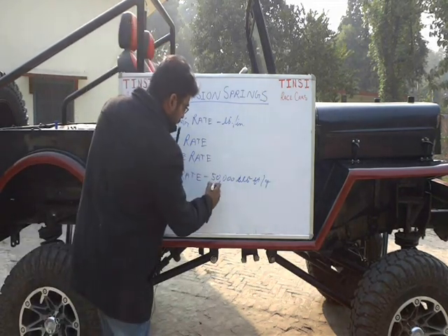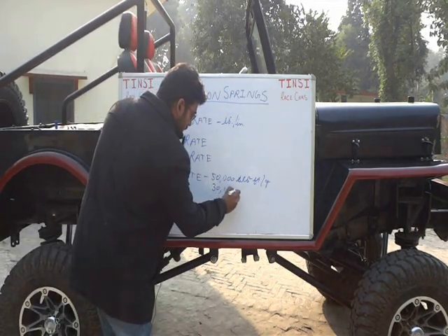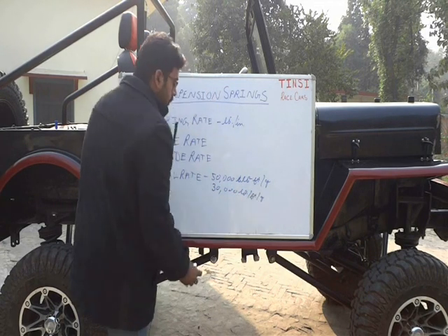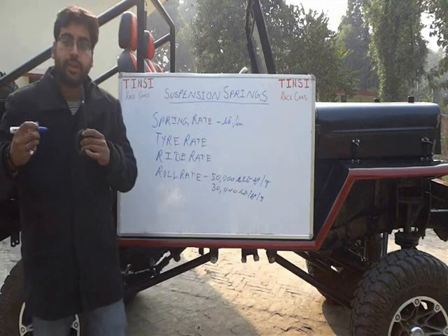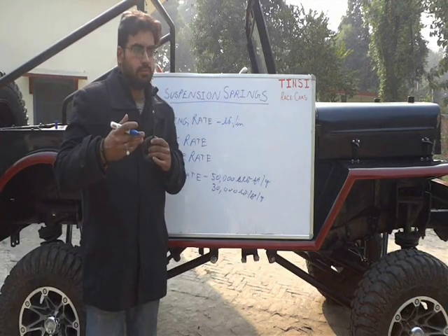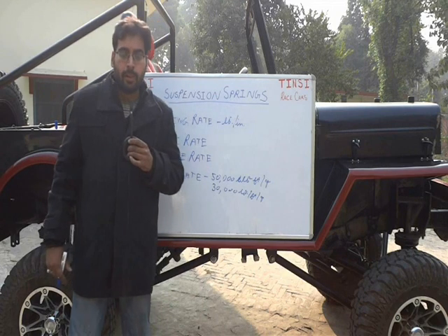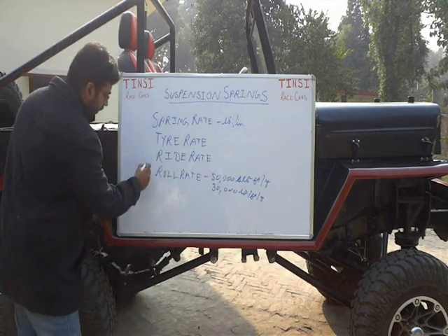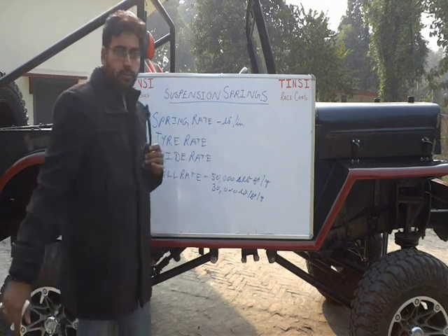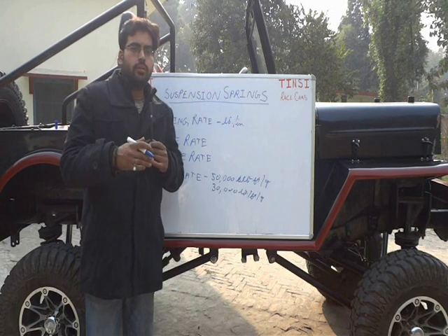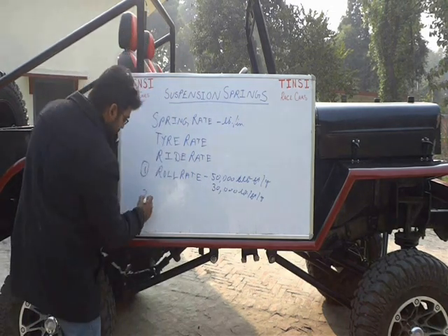For the rear, I'll go for 30,000 pound-feet per G. Okay, because this is a moment that is suggesting body roll per unit degrees of body roll. Okay, so for the first step I've started by assuming this roll rate. Now I'll go to tyre rates. Fine.